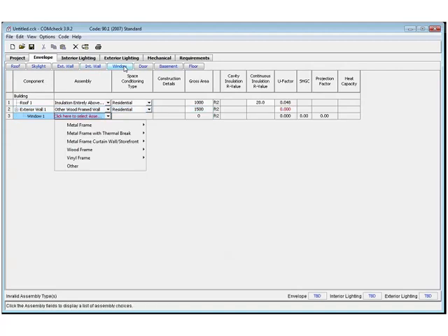Then your windows and doors, pretty straightforward. Define what type of window it is, double pane, low E. Doesn't change anything. You still have to add construction details here as far as clear or tinted. The rough opening, and if you have all the windows are all the same as I mentioned with all the same walls, total them all up, one line item. Only unless the U factors and solar heat gain, if they're different, then you're going to have to start entering those individually or group them together. So you can group like components together.